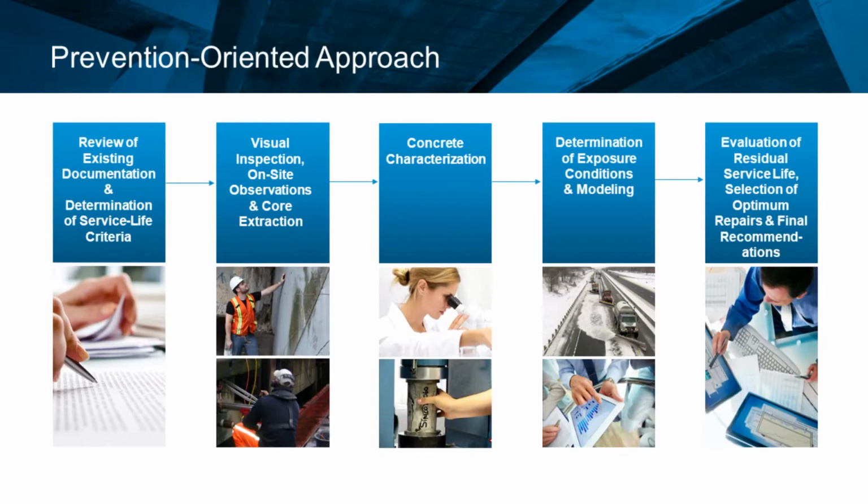So it can be more detailed in different steps. So I can mention we need to evaluate past inspection records, past testing reports. Also, another important step is field work. So this can be performed by anyone that is affected to the maintenance of the bridge, but we need the visual inspection.